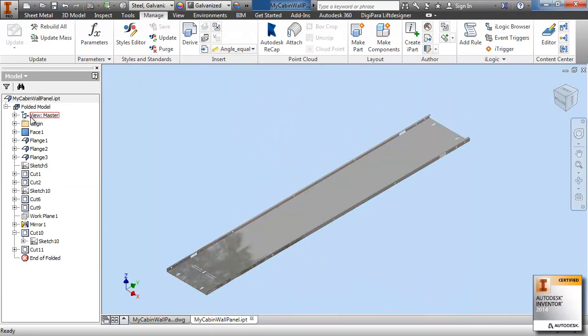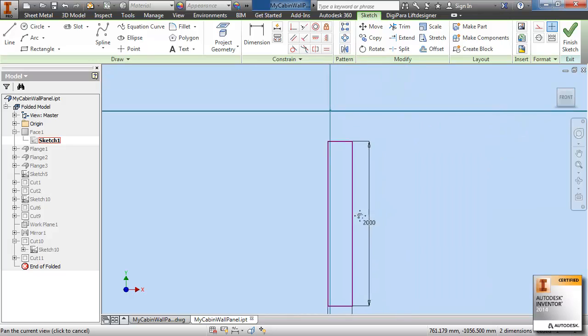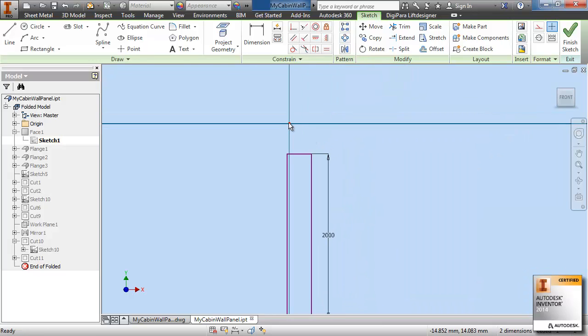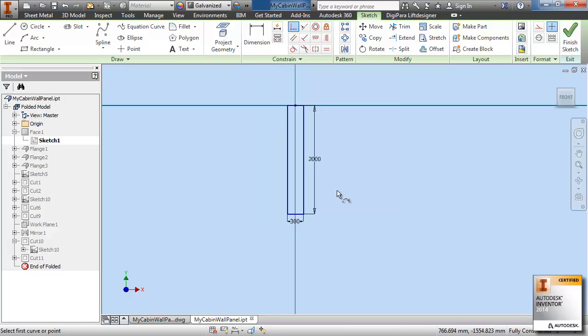Then you see what happens in this sketch here. That here is the base point of the model, and there is no relation between that. So what we should do is we should have a coincident constraint here so that this fits properly.